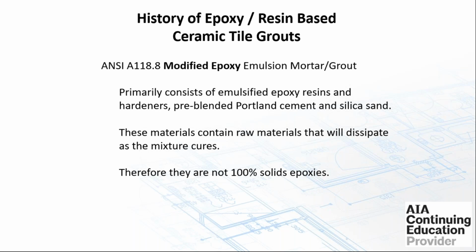So you had to be careful using it in a commercial application subject to high greases or high cleaning. You had to make sure of that, because this emulsion epoxy would break down in those applications. They were not 100% solids epoxies.